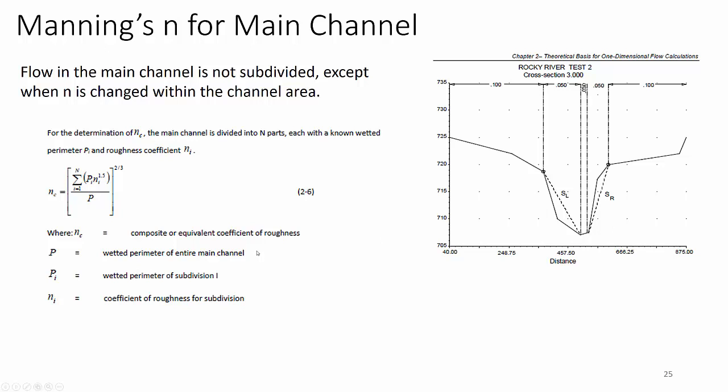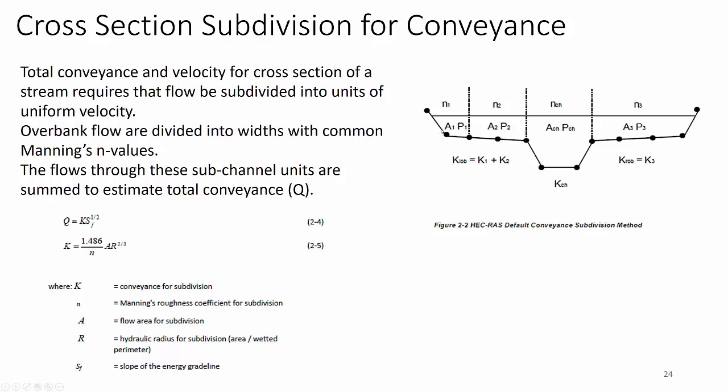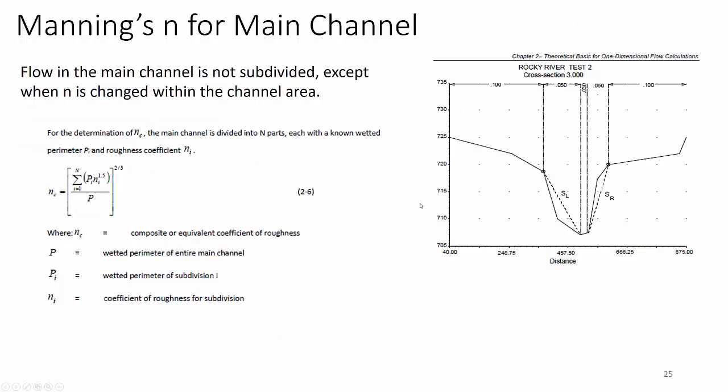We generally, in smaller streams, simplify this as the channel wetted perimeter, because usually the channels are gravel and rock with maybe some soil side slopes. And then these beds sometimes are vegetated, sometimes they're not, sometimes they're gravel. Oftentimes they're vegetated with grasses, sometimes even things like river cane. And sometimes in the floodplain, this will be forest land. So you've got to understand what those are, depending on what depth flow you're predicting, because many times this is where the riparian forest exists.